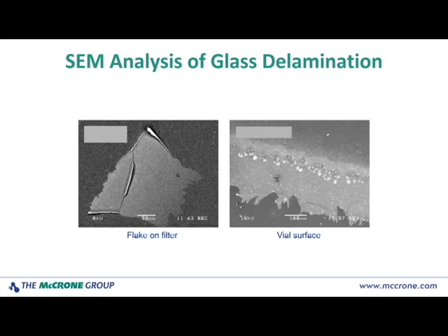The lighter gray angular feature that you see taking up most of the center of the image is a delamination flake, and you can actually see the edges curling up, so it gives you some idea of how thin these flakes are. Now, if these flakes become very small or are extremely thin, they don't impart a lot of contrast to the image, and they may be very difficult to locate in the SEM, which, as I'll show, is another advantage of going to the transmission electron microscope.